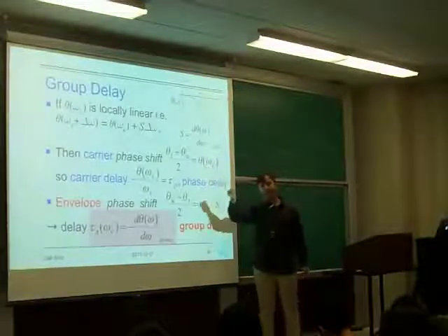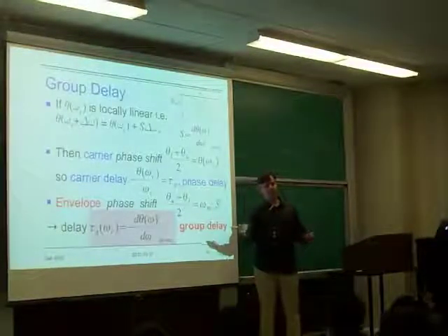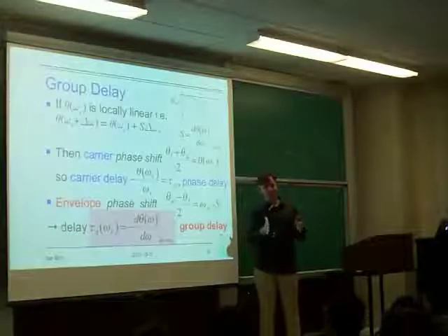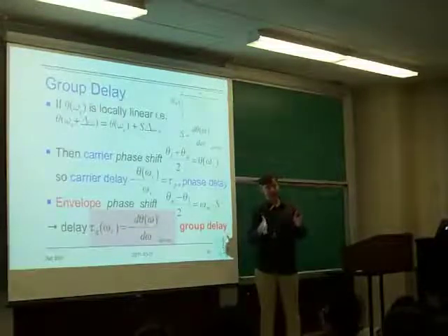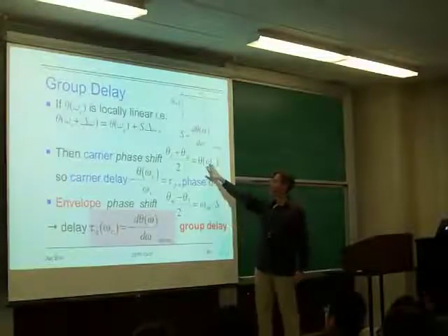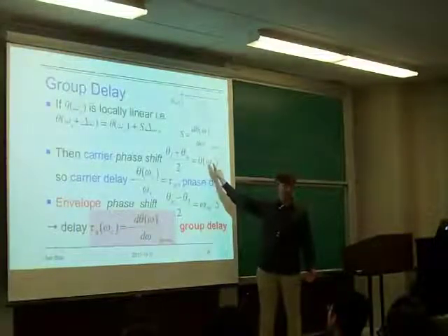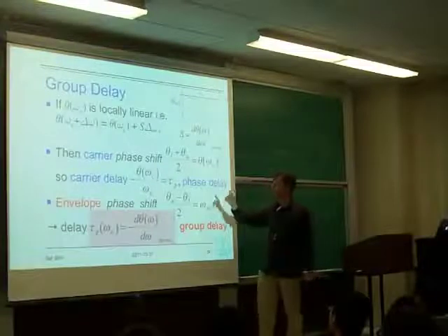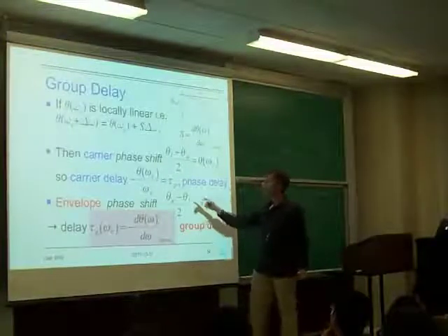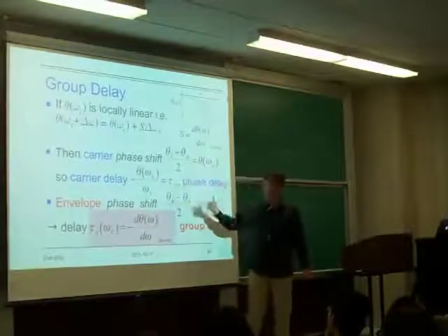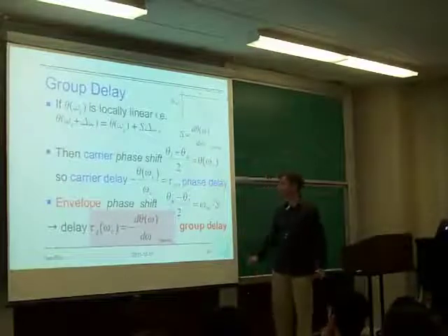So that's kind of nice that the carrier experiences a phase shift, even though there wasn't actually any energy at the carrier, it was only at these two side bands, it still appears to exhibit a phase shift, which is kind of what we expected, the phase of the frequency response at that frequency. And so that's the phase delay, what we see hitting the carrier.